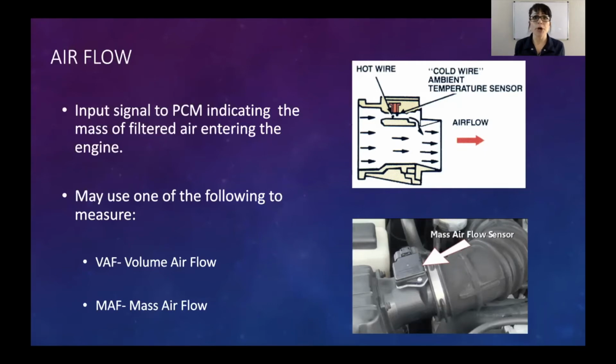That's why people put on turbochargers, superchargers, or nitrous. You're adding more oxygen, and then obviously you'll make provisions for more fuel, like bigger fuel injectors or a larger fuel pump to meet the oxygen level, right? So it's really, really important to know how much air is coming into the engine, but it's even more important to know the density or oxygen content.